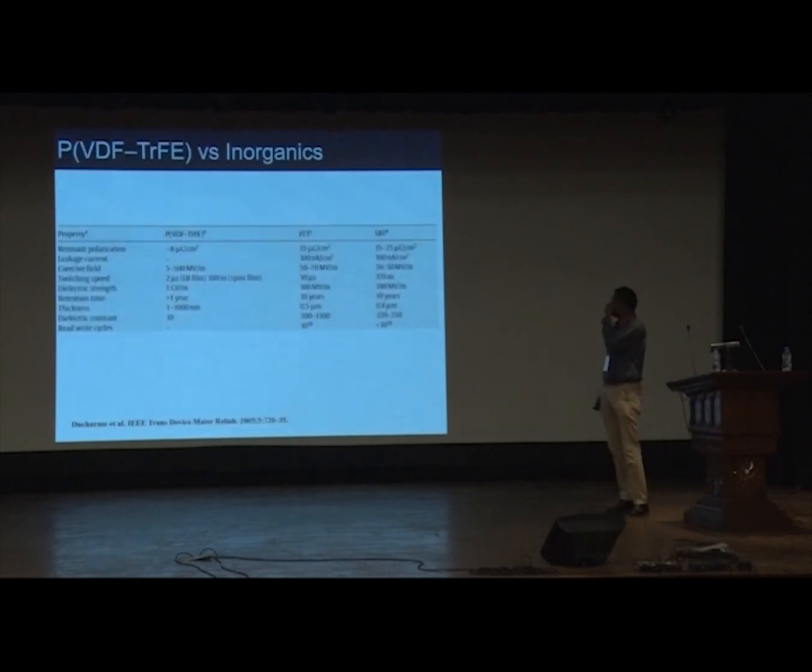When I compare PVDF with inorganic materials, there are certain issues. The issues are, if I compare various specifications like remnant polarization, leakage current, coercive field, etc., these are 2 very commonly worked upon inorganic materials, PZT, lead zirconate titanate, and strontium bismuth tantalate.